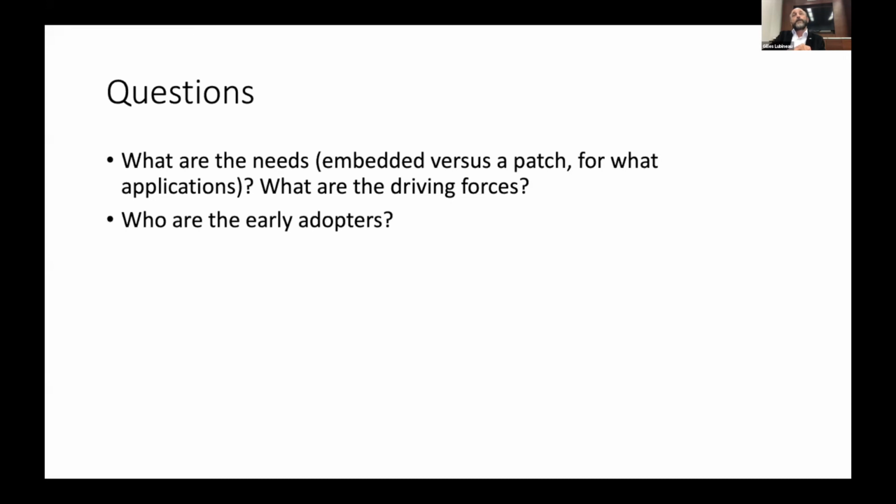When it comes to composites, I was discussing glass fibers, but this is not the solution to everything. A typical problem in the pipe industry is that when you have a pipeline with hundreds and hundreds of kilometers, how can you locate a leak, or a problem in the wall of the pipe? With a metallic pipe, it's easy because you have an electromagnetic coupling with the metal. You can put in the flow what you call a pig, a gauge that travels with the flow. But you cannot do it with a composite pipe. So this is a big question.